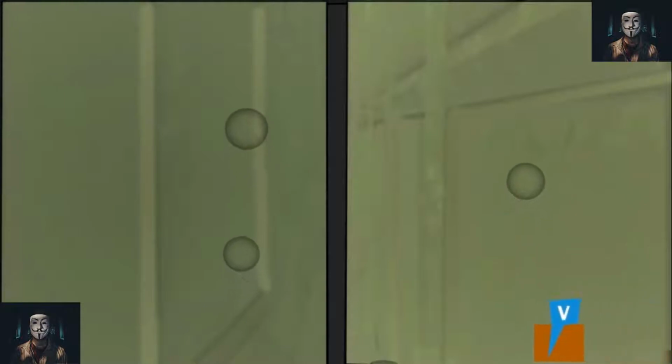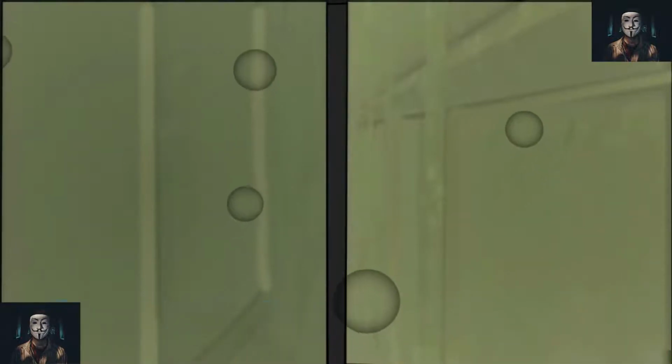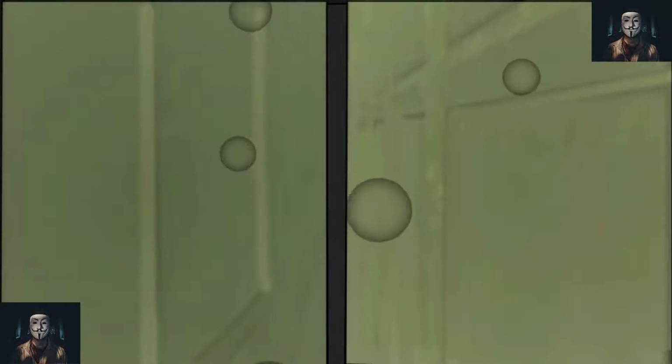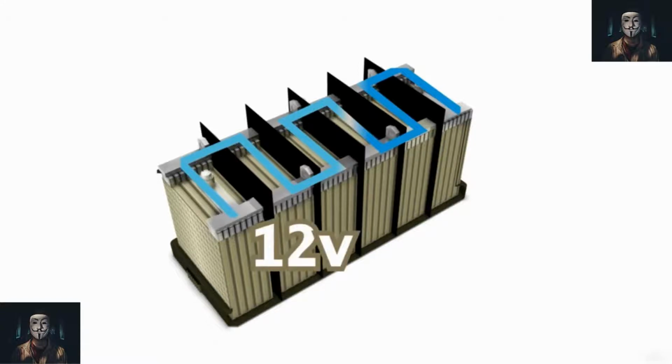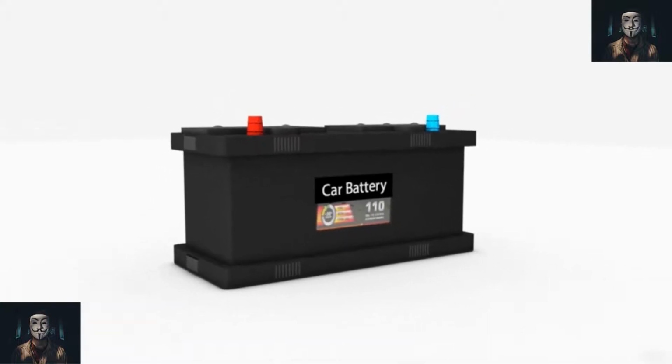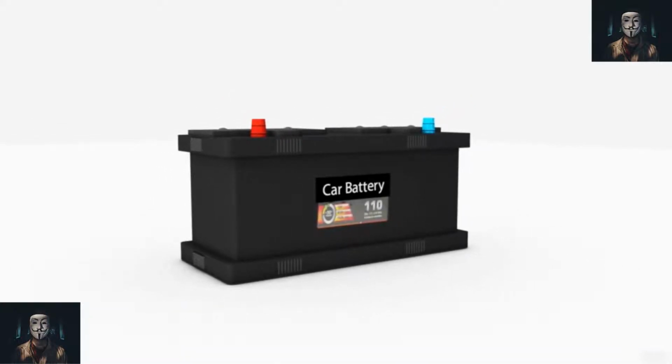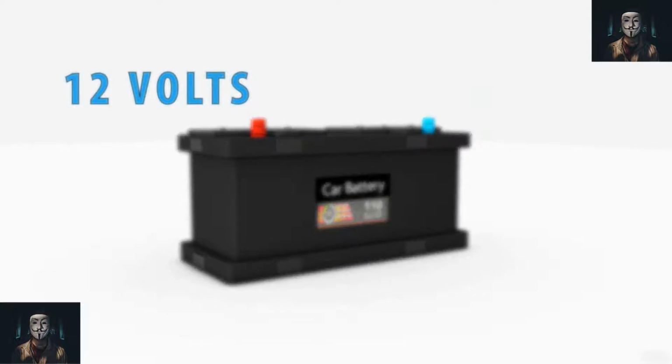During discharge, the sulfate combines with the lead to form lead sulfate. The oxygen in the positive plate is released to the electrolyte and combines with the hydrogen that is left to form water. During charging, the reverse process occurs, with the sulfate leaving the cell plates to reform with the hydrogen in the electrolyte to produce sulfuric acid. Oxygen in the electrolyte is released to reform with the positive cell plate material as lead peroxide.